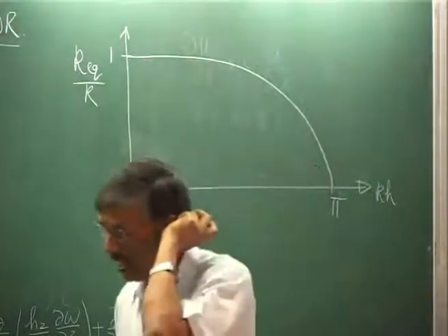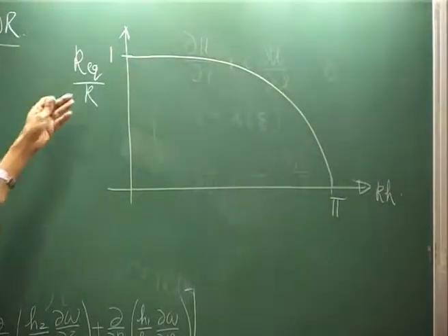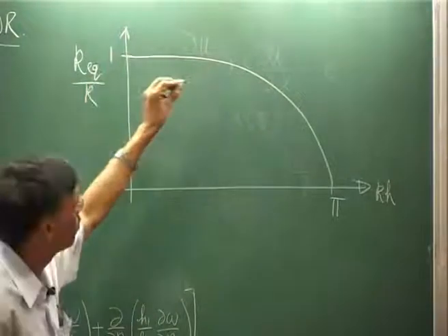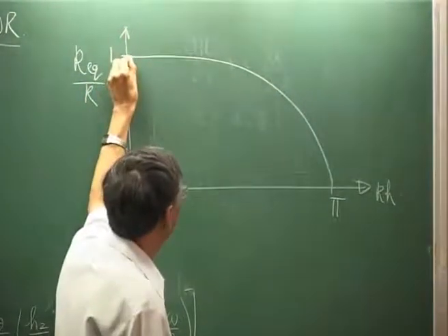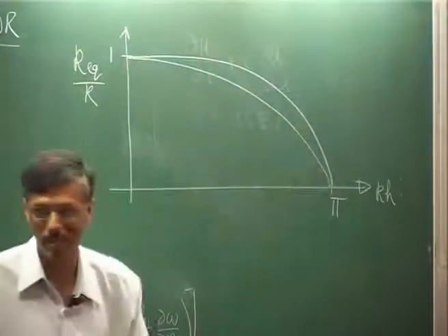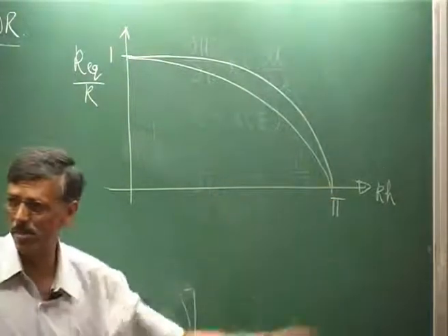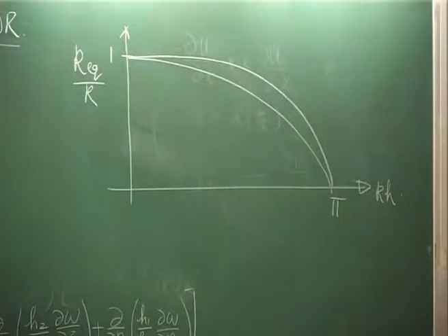So now what happens is, if I use the first derivative evaluation method twice to calculate the second derivative, what will happen? That will be like doing it twice, right? So basically you would see that it would degrade to something like this. And that means what? At the Nyquist limit, your second derivative is totally ineffective, 0, right?